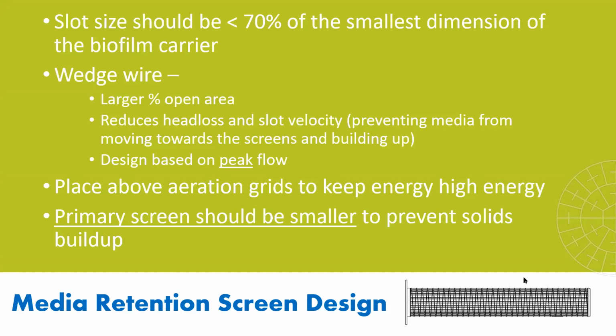What that open area allows us to do is reduce the head loss in the system and reduce the slot velocity, which is the velocity of the water moving through the open area of the screen. Now, this is important for MBBR design because we want to make sure we have a low slot velocity so that we don't have the media migrating towards the screen due to the velocity of the water, right?